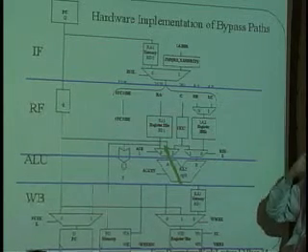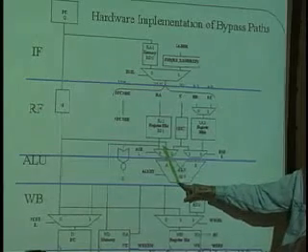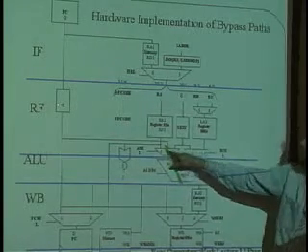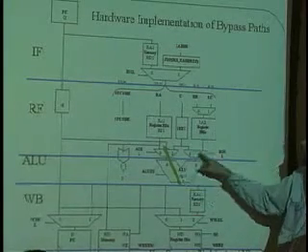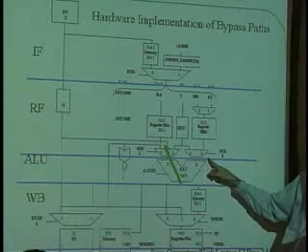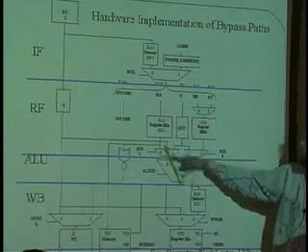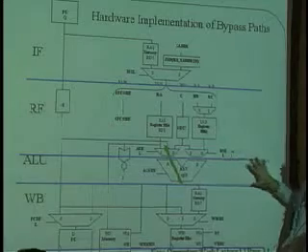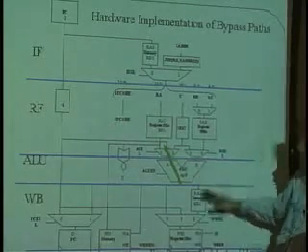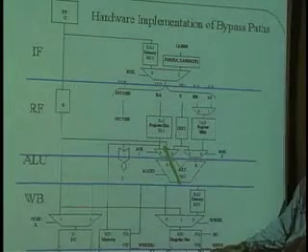But we can just short circuit that by pulling the data off of here and putting it into this multiplexer. Let's say we're going to feed it into the left-hand side. We're also going to feed it into the right-hand side because we're not sure which side we're going to need it by. And that feedback loop only has 1 register in it. Just like our old feedback loop, before these 2 blue lines were here, down at the bottom only had 1 register in it.